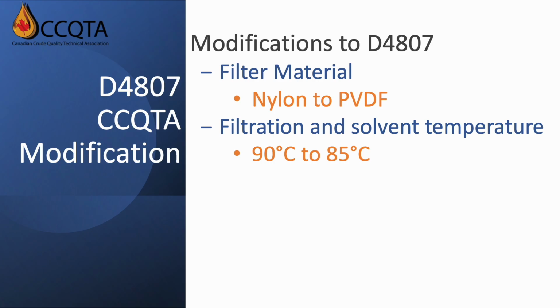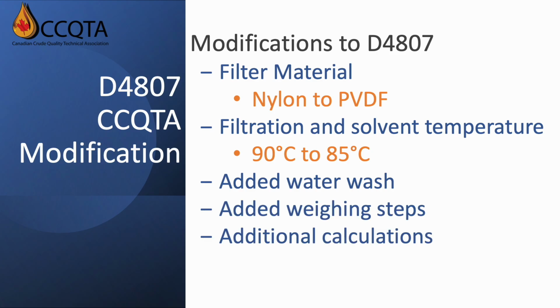The purpose of the elevated temperature is to ensure any wax crystals are liquefied, allowing them to pass through the filter, so this minor temperature change should have a negligible impact. Next, a hot water wash has been added after the toluene wash to remove water-soluble salts. Then additional weighing steps were added to allow quantitation of both the toluene and water-insoluble solids.